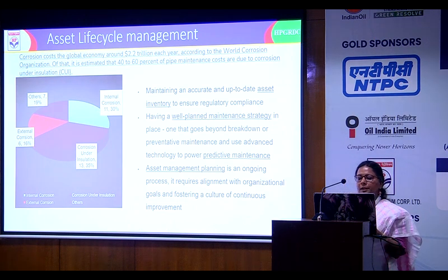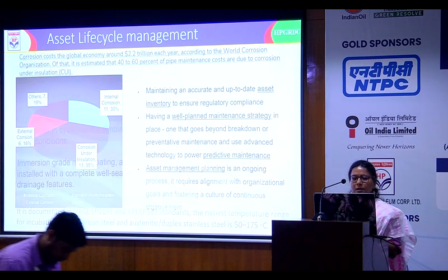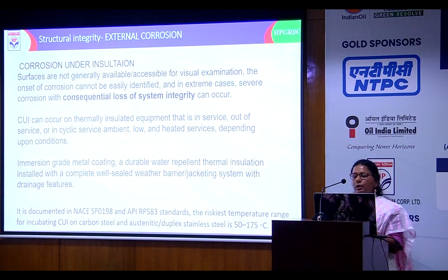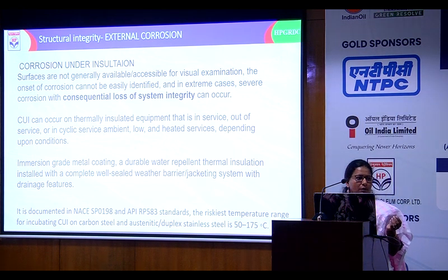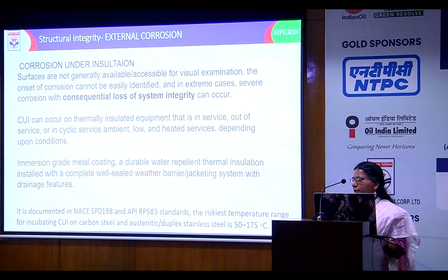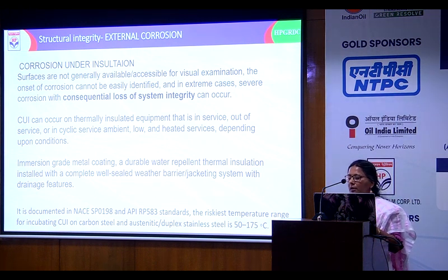There has to be predictive maintenance, and the asset management planning falls in place thereafter. So just now I told you about the corrosion under insulation. The surfaces are actually not visible by eye. Right now, when Dr. David from Shell showed that monitoring has been done, it's a visual thing. But this corrosion is occurring under insulation, so we are not actually seeing what is happening underneath.